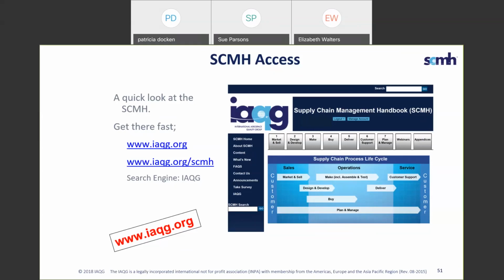The presentation interprets the word control as measure, check, inspect. Does it also encompass the steps which actually produce the quality characteristics? Looking at all the steps influencing a characteristic, quality cannot be produced by checks. Yes, that's a great question, and I hope we conveyed that in the presentation, that it's not just about inspecting product characteristics and catching them and trying to prevent passing them on. You really want to look at the process inputs, those inputs that are the key things that are going to make that feature or that characteristic.